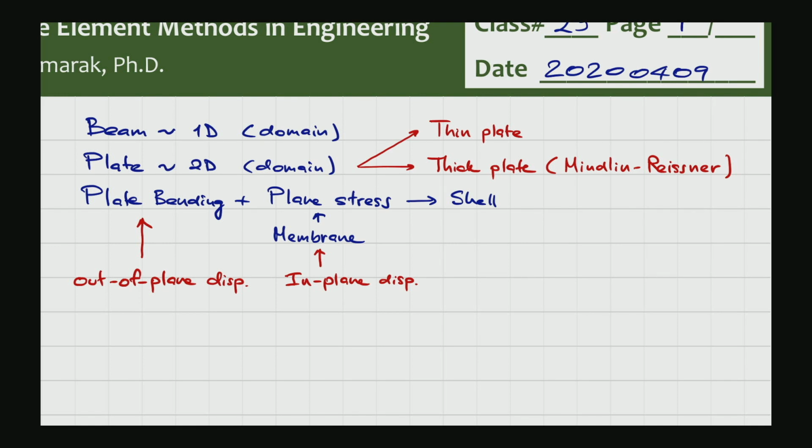So with this, it behaves better than the thin plate. Thin plate is the Kirchhoff plate bending problem. I decided to omit the thin plate bending because I believe that this thick plate formulation is actually easier to use and more useful to do.